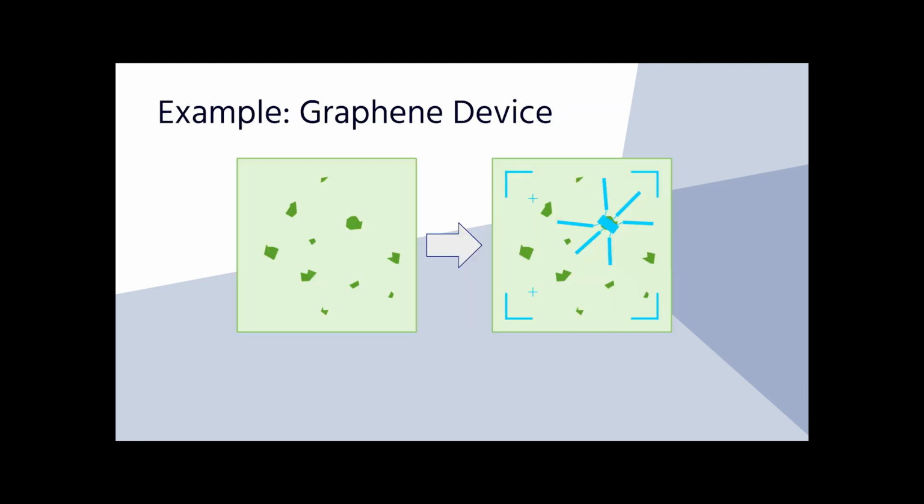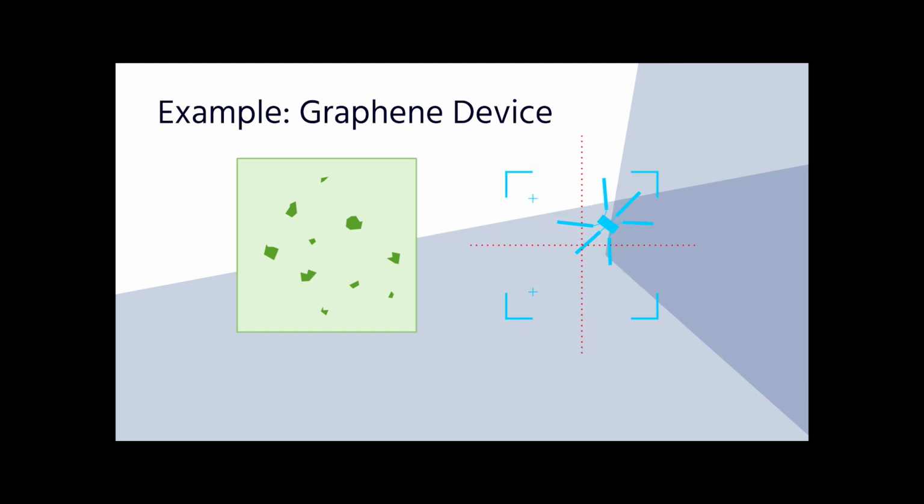We will use a pretend graphene sample to walk through pattern placement. We want the electrodes to be correctly placed over one particular graphene flake. How do we go about doing that? The easiest way to think about this is to consider the origin of the design file. I want to map that origin to a known stage location. Where things get tricky is when you can't look at the origin. In this case, the origin occurs over one of the electrodes. So if we navigate to that location on our chip, we will have exposed that region.